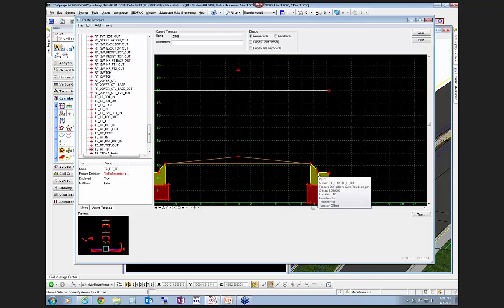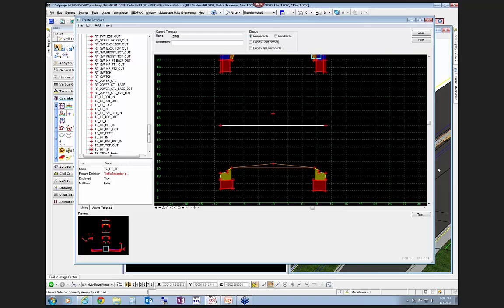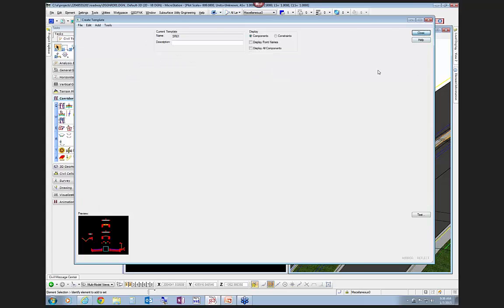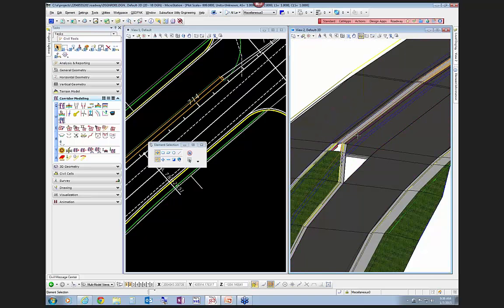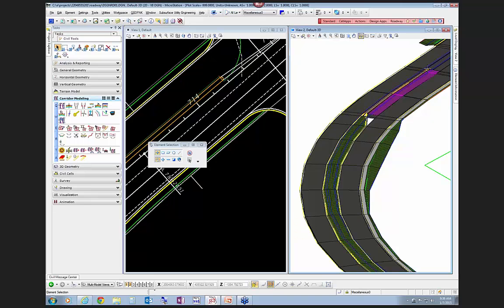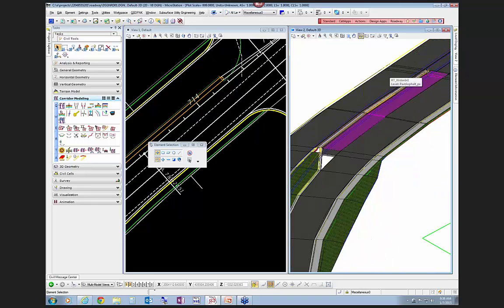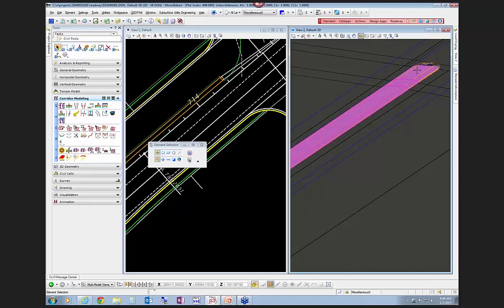So that's why you're seeing in the model those 3 different pavement segments, okay? So that's why, as you know, it continues along this same slope. So if it's super elevated, it'll continue up. But what you'll end up getting is a sloped pavement up to this edge of traffic separator, and this traffic separator is no longer at the same elevation. It has to be elevated a little bit in order for it to meet this pavement.